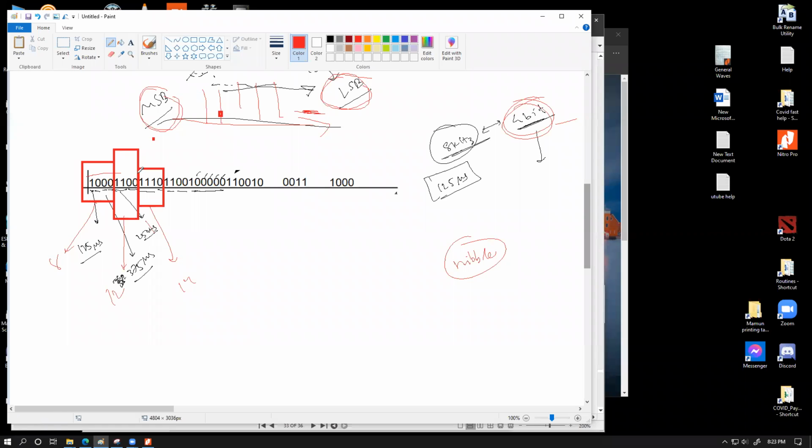But if you are doing this whole thing of serial and parallel conversion in a stream like this, the MSBs and LSBs are all important, because it is really important exactly where you are chopping these numbers. For example, if this chopping location gets shifted by only one space, you'll have a whole mess of data. If all of these rectangular boxes shifted one digit to the right, you would not be getting the original data. You'll be getting a whole lot of non-similar data that you did not send. So that's the significance of this whole thing.